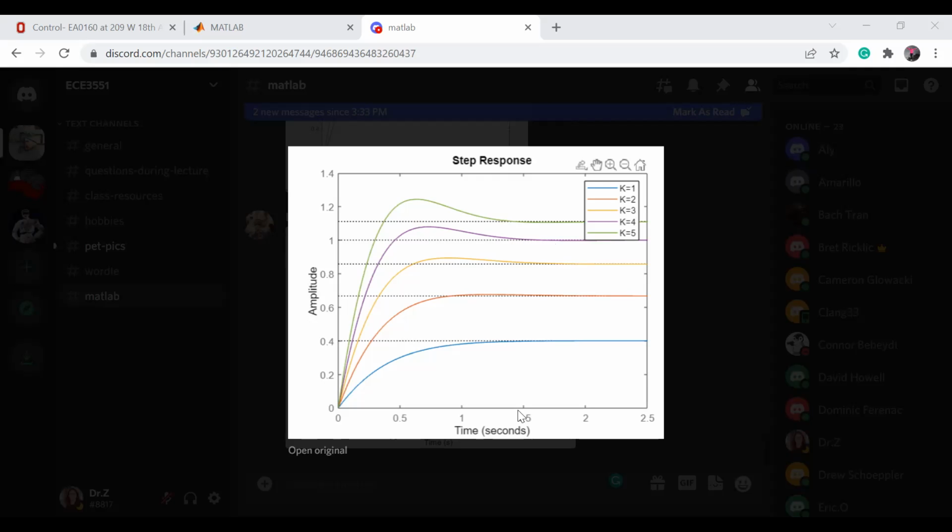All right. So now we'll see, in the case of this purple k equal to 4, that this is happening around 1.5 seconds. Now, depending on your system, this might be too slow, right? So you will go and check your other requirement: what should be the settling time? Because that's the settling time, right? It might be your settling time should be 0.5, for example.